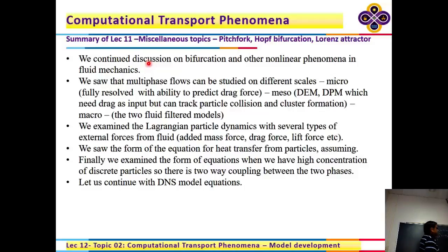If you write out the expanded Navier-Stokes equation in cylindrical coordinates and start simplifying it, you will find that this term drops out. Even if you select unsteady in COMSOL, it will keep this term and integrate, but it will eventually be 0 when it reaches steady state. And each one of these terms would be 0. Why is that?